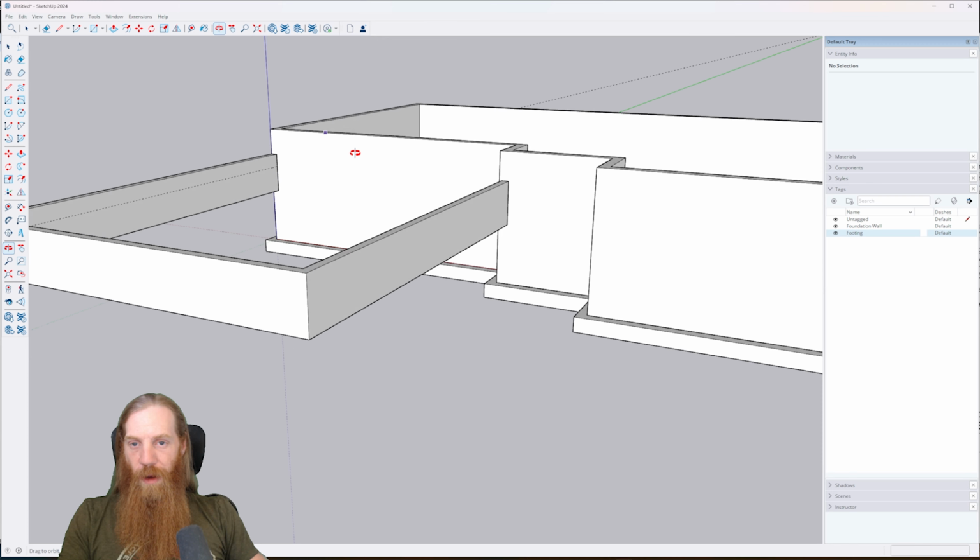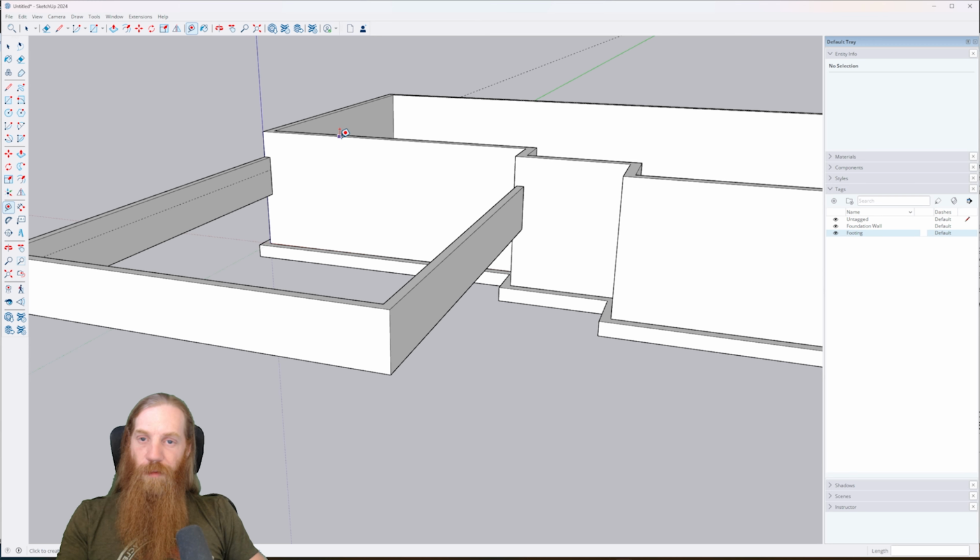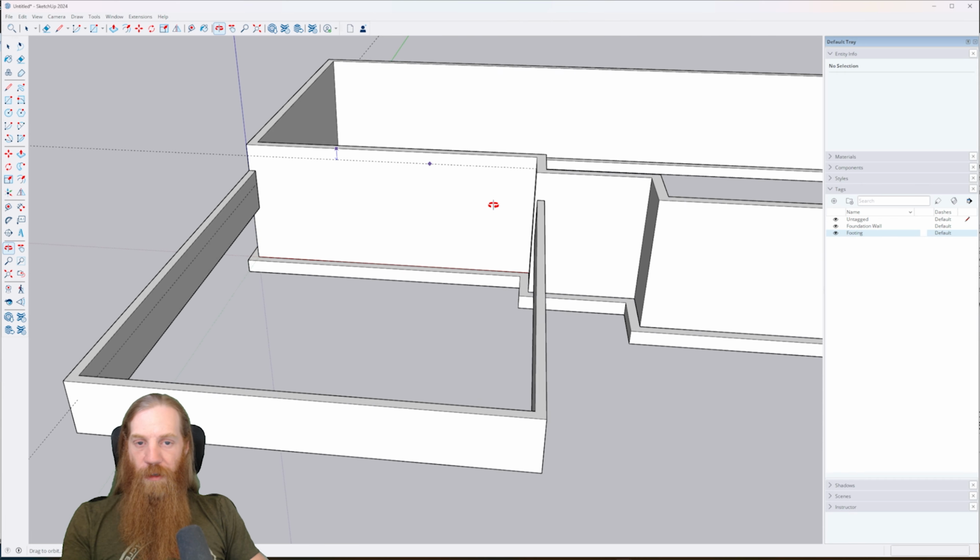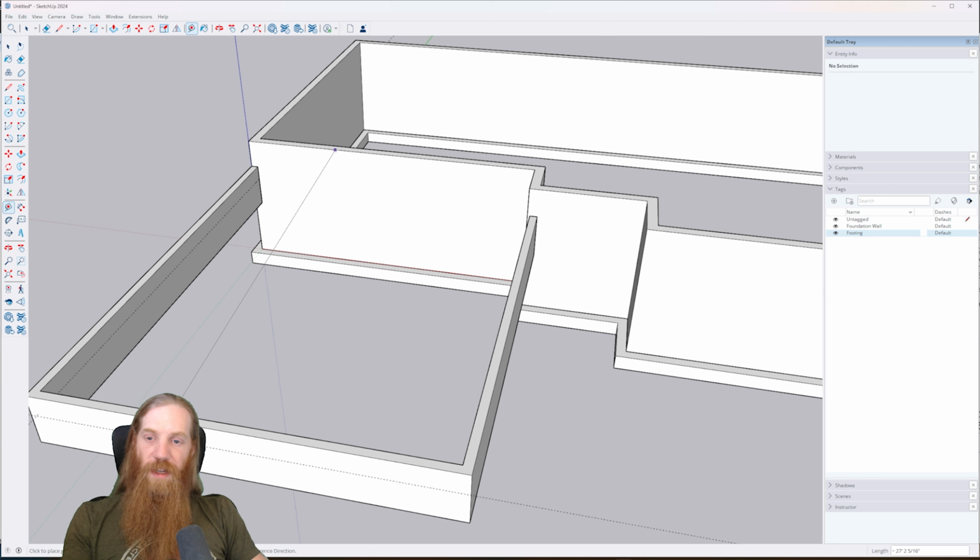But anyways, let's see how far down that is from the top of our foundation wall, because we're going to have to create stairs inside the garage that go from the slab of the garage up to the door that goes into the house, right? So I'm curious what that height is. 3 feet, that's going to be like 4 steps. Not a problem at all, right? We can easily fit 4 steps and a little landing for the door into the back of this garage here. And because we pulled the garage out 27 feet, you're still going to have plenty of room for your vehicles.